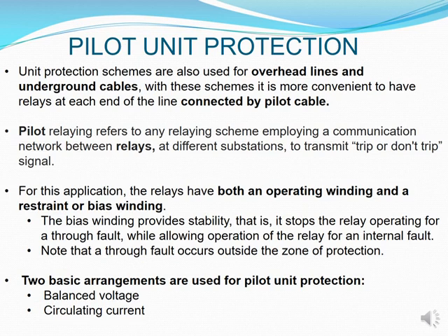So our pilot relaying refers really to any relaying scheme employing a sort of communication between these relays that you have at each end. And it usually would then transmit a trip or a not to trip signal. And for this application, your relays have both what we call an operating winding and a restraint or bias winding. So on our bias winding, really what it is there for, it provides stability